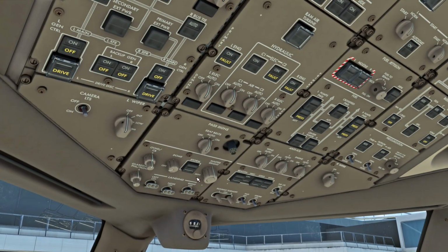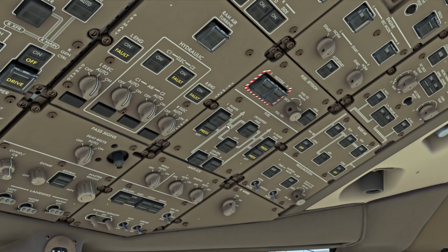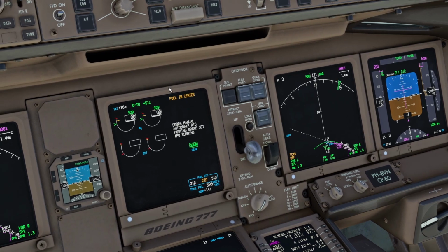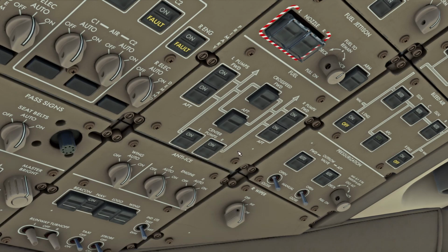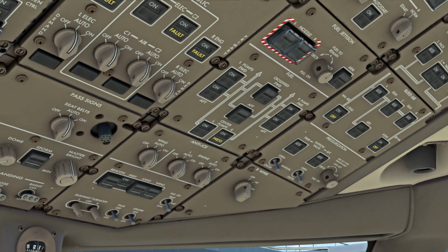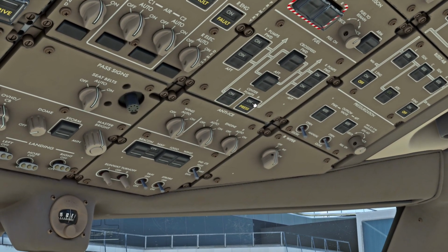Okay, so go down, seatbelt is already on. Then the fuel pumps, again, we turn them on. Also this one, even though the APU has already been using it in the background, we have to physically turn these fuel pumps on as well. And in the center pumps you would get an ICAS message, fuel in center, and that indicates there's fuel in the center tanks as well, so we have to turn those pumps on as well. Pressure lights are being extinguished, except for this one, and that's also correct. This is also simulated in the background. This pump is at the moment being load shed by the aircraft system logic.